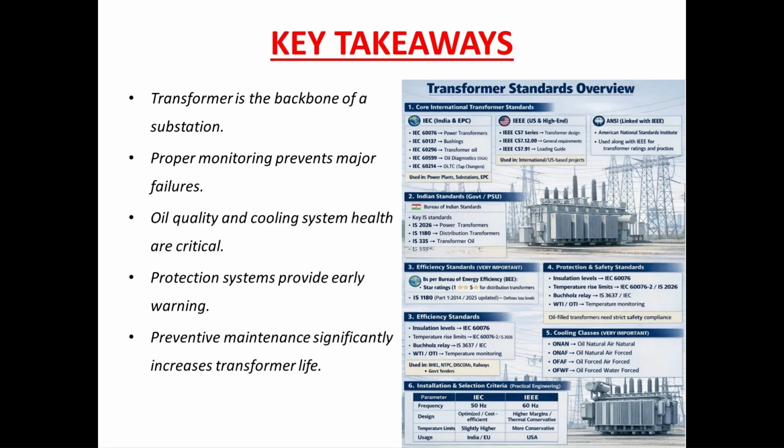So these are the standards available for the core, the transformer testing, for protection, for safety, for efficiency, for cooling class installations, and based on these guidelines only, the transformers should be treated. And as we know, transformer is the backbone of a substation. Proper monitoring prevents major failures, and the importance of oil quality and cooling system are very much critical for maintaining the system health.